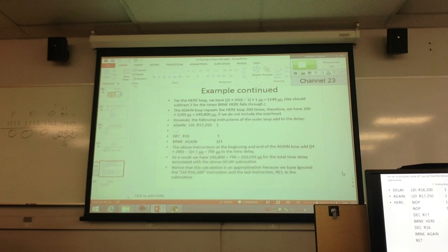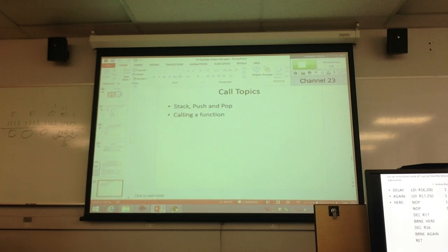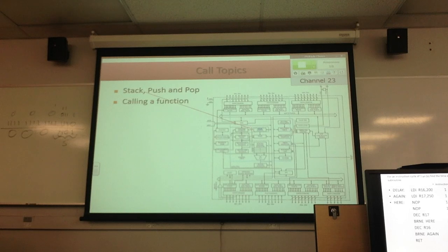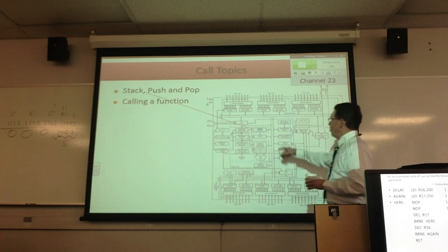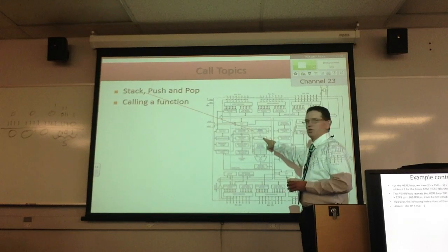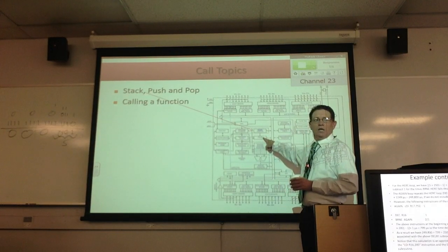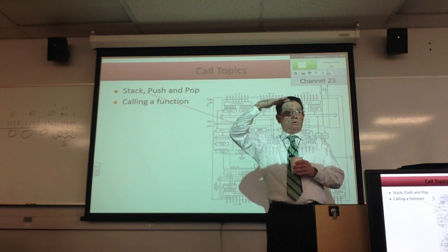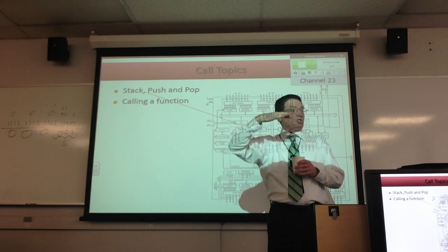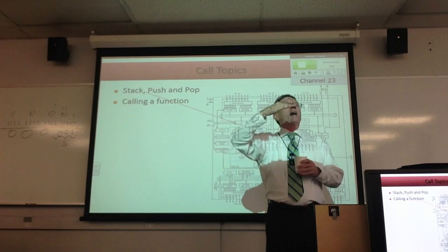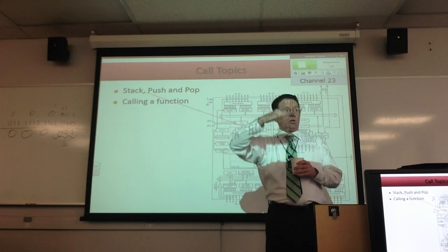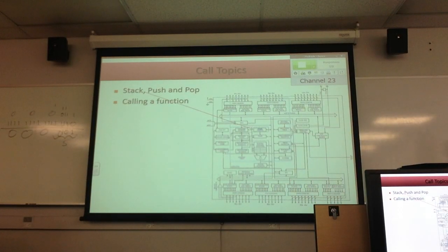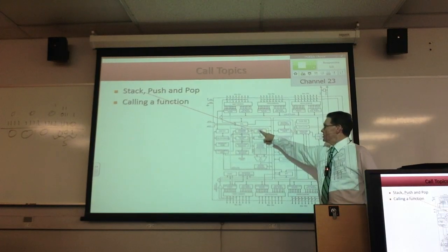All right, let's see, I'll pop this up here. Now we get to the stack. In hardware, the stack pointer sits right here, and notice it's tied into SRAM. The last of the special function registers is the SREG, which is a status register. The one right before that is the stack pointer high and low. They're the last two before the status register. But in hardware, that's where it sits.